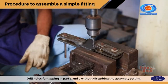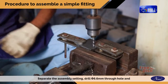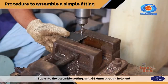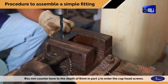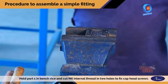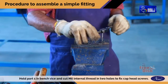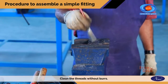Drill holes for tapping in part 1 and 3 without disturbing the assembly setting. Separate the assembly setting, drill diameter 6.6 mm through hole and diameter 11 mm counter bore to the depth of 8 mm in part 3 to enter the cap head screws. Hold part 1 in benchwise and cut M6 internal thread in 2 holes to fix cap head screws. Clean the threads without burrs.